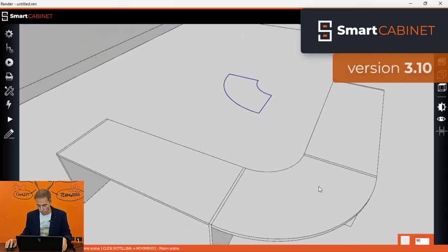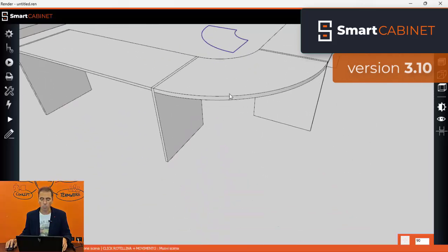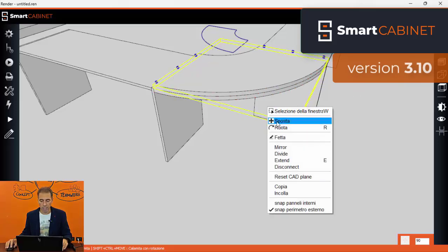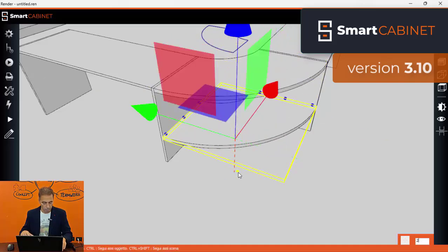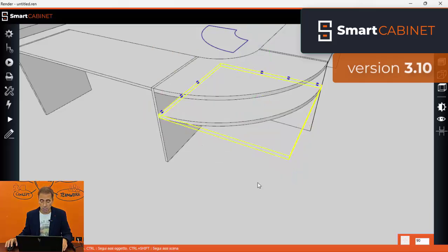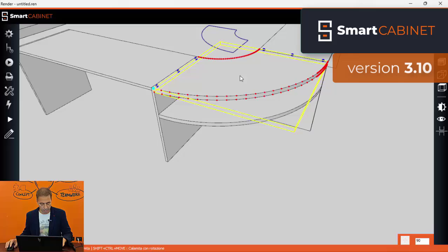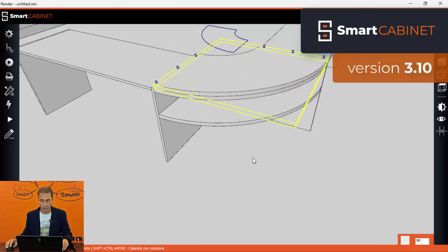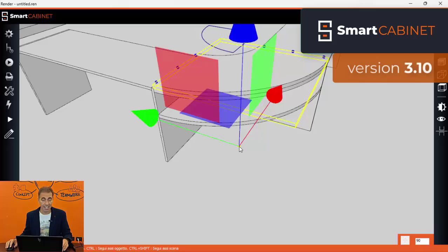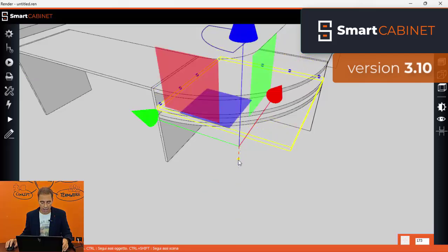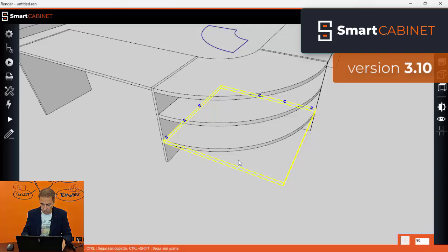Great. When we make something like this, at the end, we have the possibility to say, okay, great, I want a copy. In this case, we can also move this element on the axis. So we put, for example, 250 millimeters. Then we make another element, again another copy, great. And maybe we want to move on the z-axis, again, by 500 millimeters, for example.